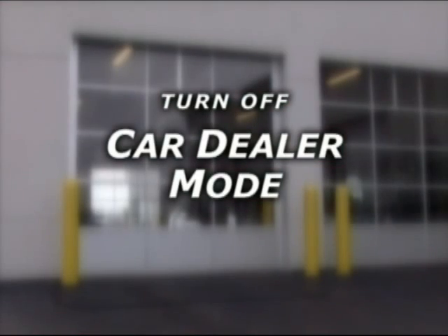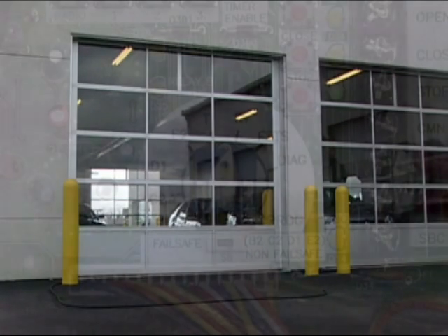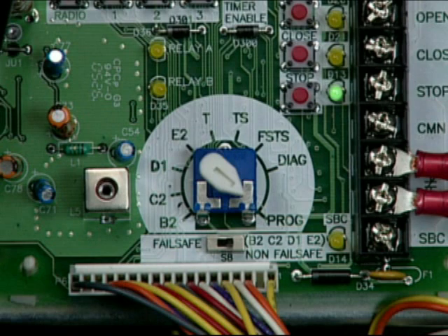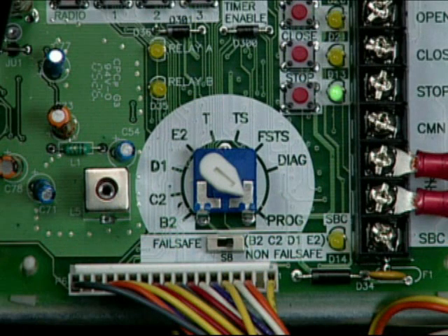To turn off the car dealer feature, begin with the door in the fully closed position. Turn the selector dial on the logic board to Program. Press and release the timer button and the timer enable LED will turn on. Press and release the MRT button. The timer enable LED will blink rapidly 3 times. Press and release the timer button and the timer enable LED will turn off. To finish programming, turn the selector dial back to the desired T, TS, or FSTS wiring type.